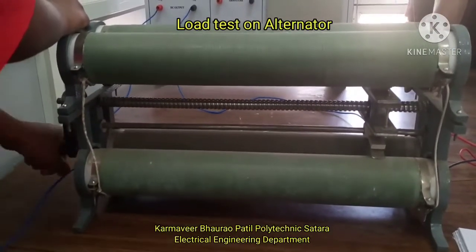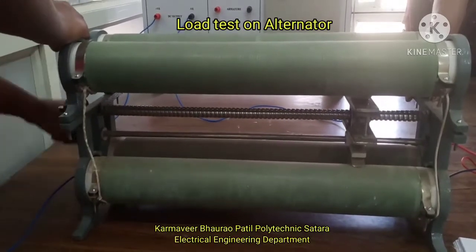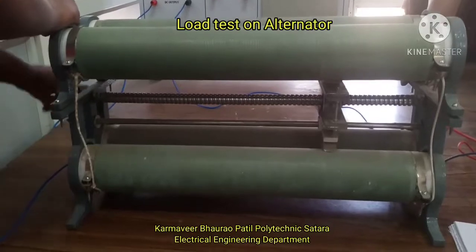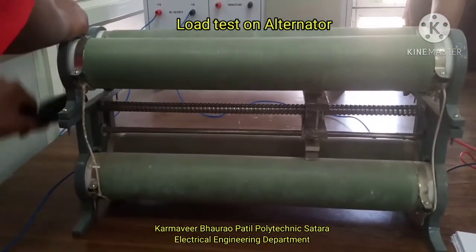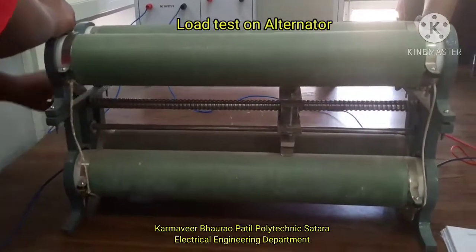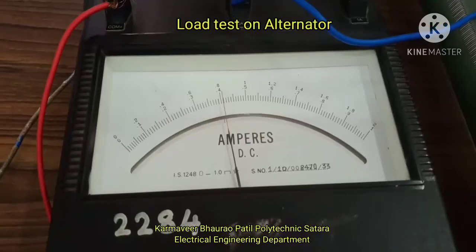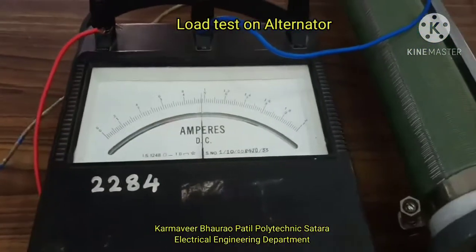We increase the excitation till we get the voltage to the rated value, but to be on the safe side, we are increasing the excitation current till the alternator shows a voltage of 350 volts.